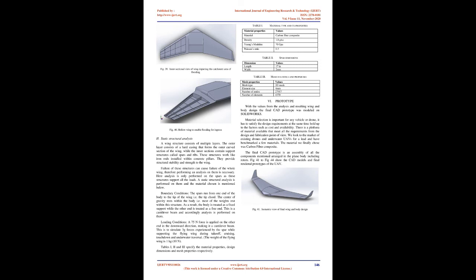Stability analysis defines the dynamic stability of the airplane in flight. For an airplane to be stable, there are prerequisites. The prerequisites are confirmed through observing the CM vs alpha and CM vs CL graphs. Both curves on the graphs must be negative for longitudinal stability. At zero moment the lift must be positive. The center of gravity, COG, must lie within 15% to 25% of the neutral point.